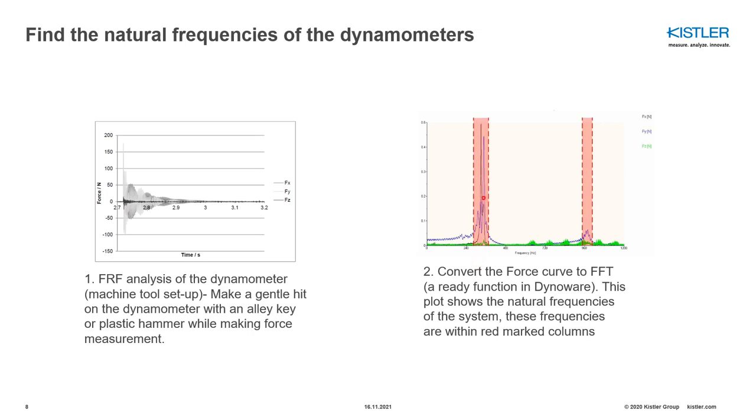And of course, this also indicates that if you are using certain RPMs and certain tool path passing frequencies and so on, you should avoid being close to those frequencies. Otherwise, you will excite that and you will be measuring that.